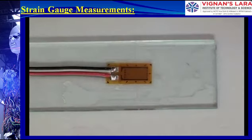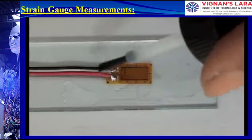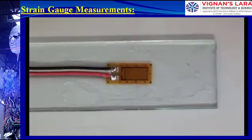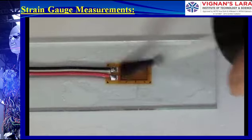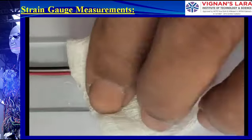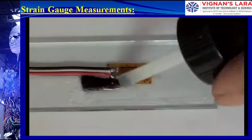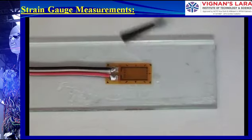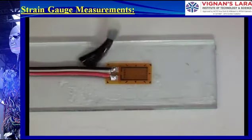The strain gauge and solder joints are washed with M-line rosin solvent to remove all traces of flux residue and blotted dry with a gauze pad. Cleaning with rosin solvent is repeated a couple of times to ensure complete removal of flux from the area.